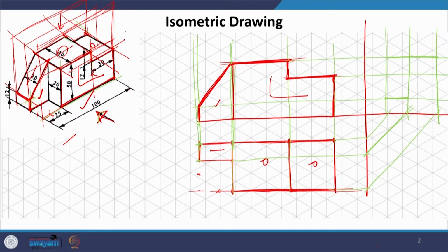Now, in the side view again we will get the same straight surface here, and at this level we will have again a straight surface, but it is going to go behind this line, right, because we are seeing it from this side. So, we will actually have a dotted one here, and in the front we have this vertical surface which is what we are getting here.